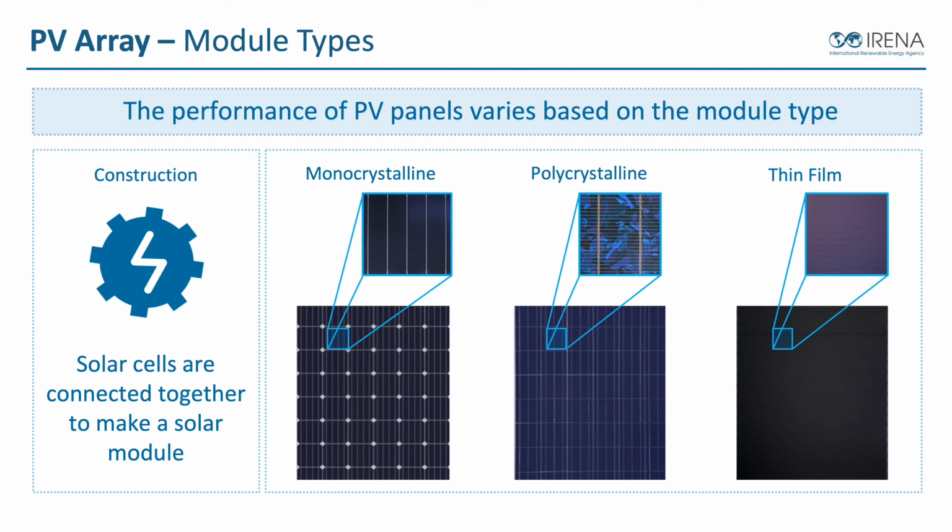There are three primary types of solar cells available in the market: monocrystalline cells, polycrystalline cells, and thin film cells. The vast majority of the solar market is monocrystalline and polycrystalline, which makes up about 90% of the global supply of solar energy. So the majority of solar anywhere in the world is monocrystalline and polycrystalline. They're both very good products, and in theory, monocrystalline is a little bit more efficient than polycrystalline if we look at efficiencies.